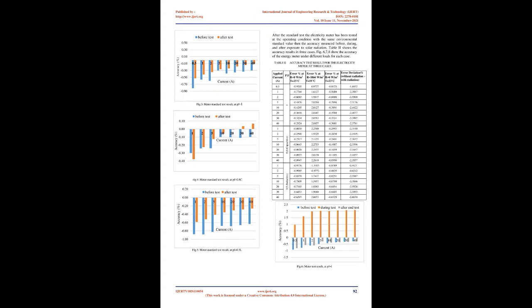The output irradiance of the designed simulator equals 1066 plus or minus 15 W/m2 at 26 cm distance from the lamps to the test area, with non-uniformity of 8.5%, and the test area is sufficient to test one electricity meter. Figure 2 shows the radiation distribution inside the chamber during the test.